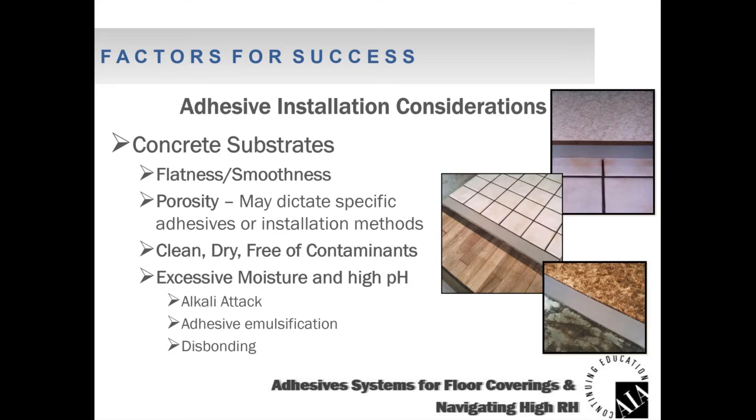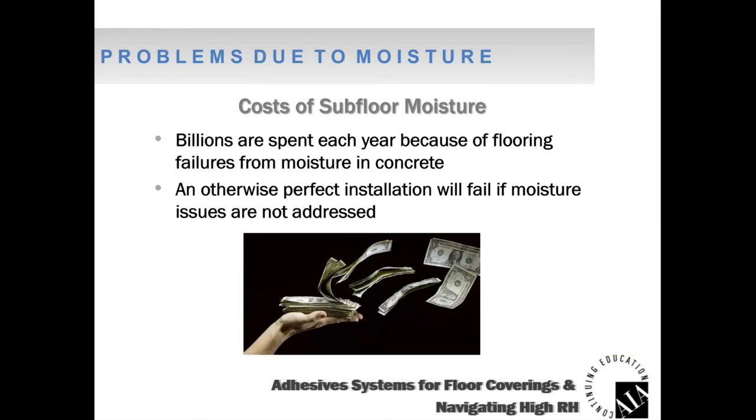Certainly with any installation, we need clean, we need dry, free of contamination. And we certainly have to pay attention to excessive moisture and pH. Follow the floor covering and adhesive manufacturers with regard to that. So speaking of moisture, good segue to get into here.